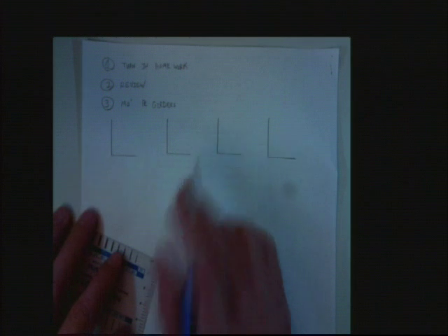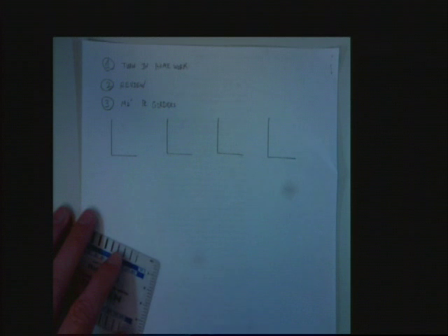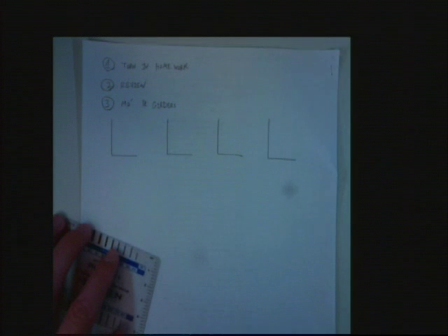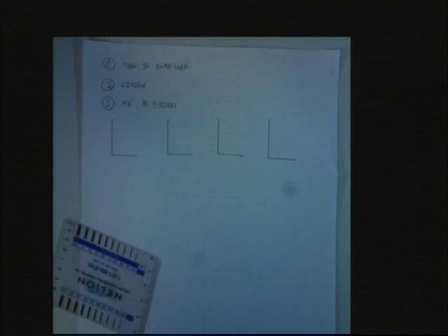Now, what is the goal with a plate girder? Why would anyone want to build a plate girder? Why wouldn't you just use a rolled section? What are the benefits of the plate girders? You can optimize your web, is probably the biggest one. Really skinny down areas you don't need, right? And webs happen to be the section that's most often skinnied.